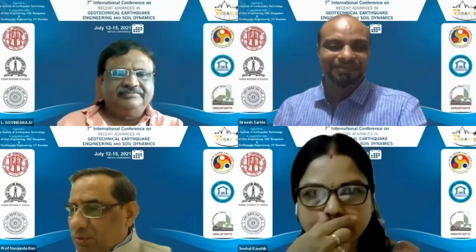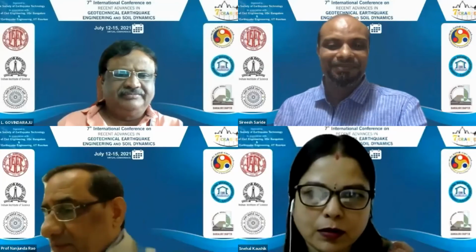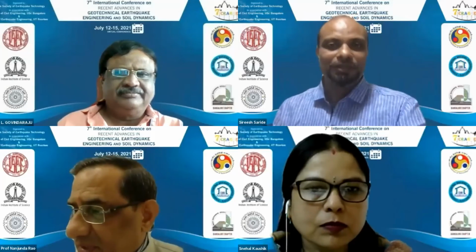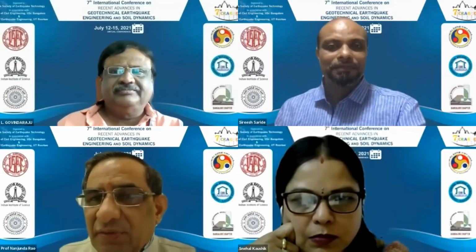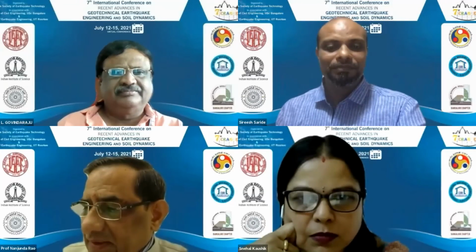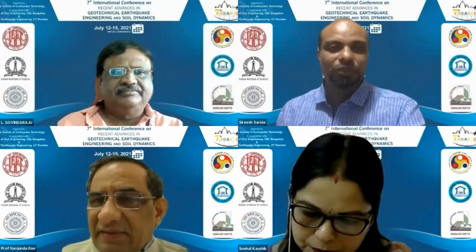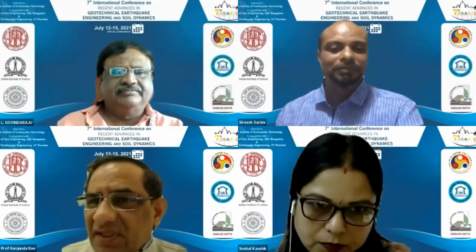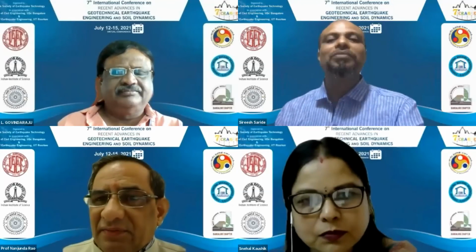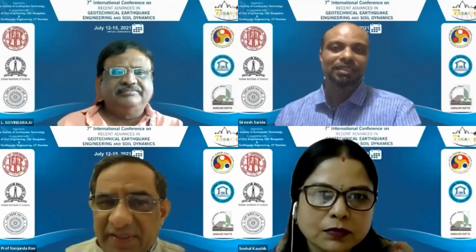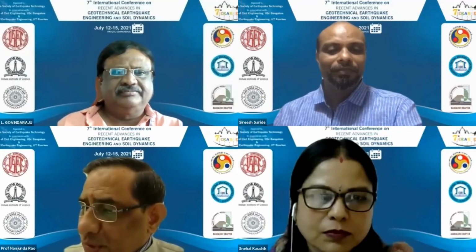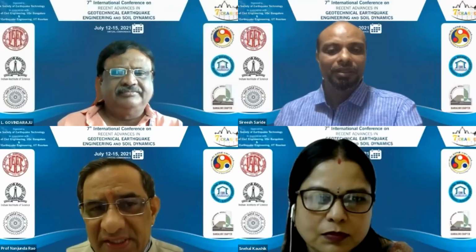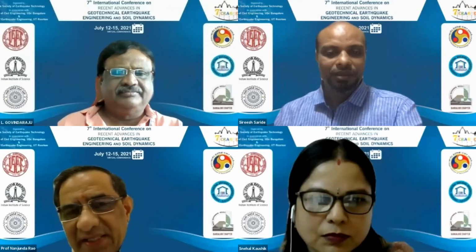Again, Professor Sireesh, thank you very much for a very nice presentation. However, I would like to make some comments and seek some clarifications from you. You said that you are using fly ash and alkali as an activator. So this is similar to our geopolymer kind of thing. This is geopolymer, yes, alkali activated. So the sodium hydroxide solution you're using, what is the molarity of the solution?